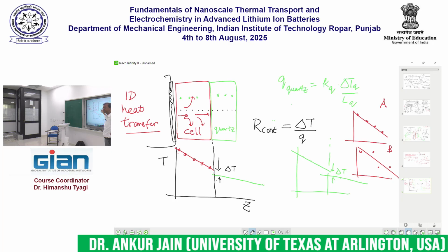If instead of it being removed simply by the air, I have a cold plate which is cooled by water, then by measuring the flow rate of the water and the inlet and outlet temperatures, m dot Cp delta T of the water tells me how much heat is being picked up by the water, right?